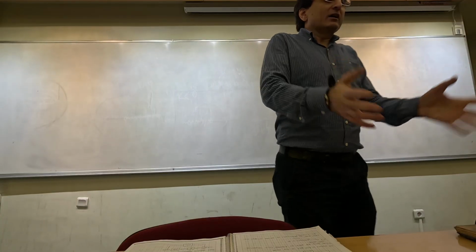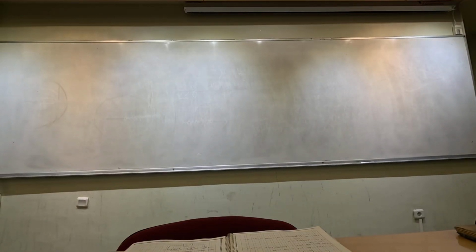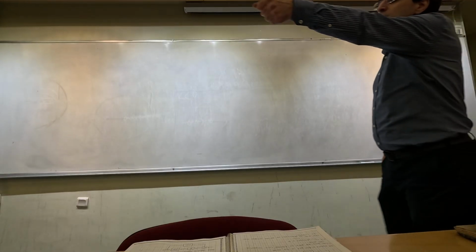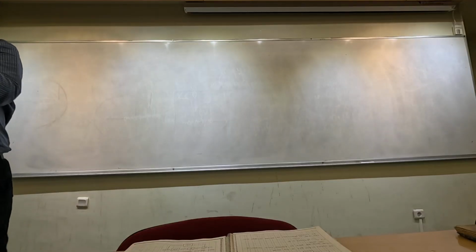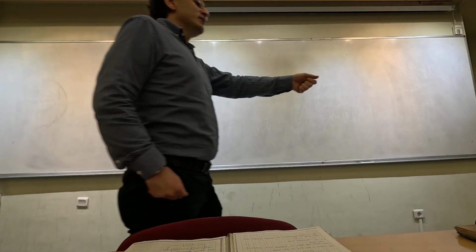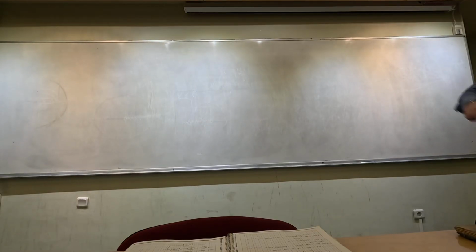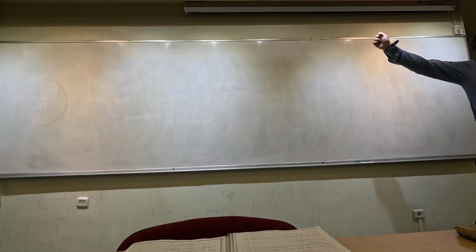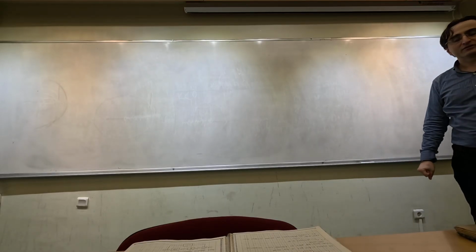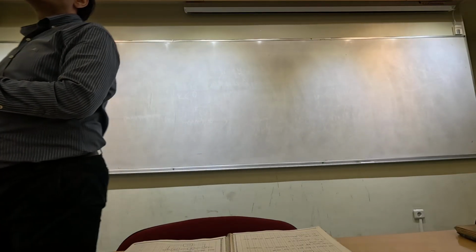Okay? So suppose that you are given a black box and you don't know the transfer function, then I can apply some sinusoids at different frequency to that system. And then I can look at the outputs. In the outputs, I will see an amplitude. If it is a linear time invariant system, I will see some amplitude change and the phase change. If I mark them on a Bode plot as some points, as the magnitude and the phase of the system, then I can always obtain a rough Bode plot from an open loop system.